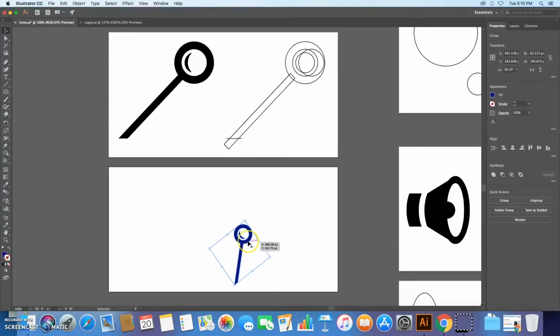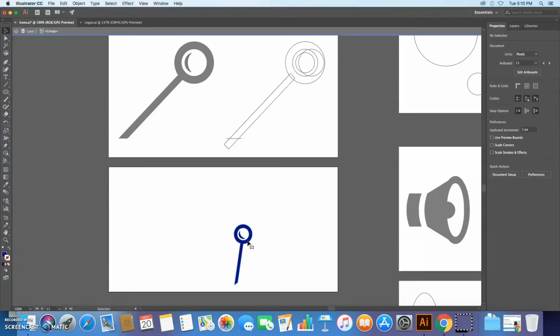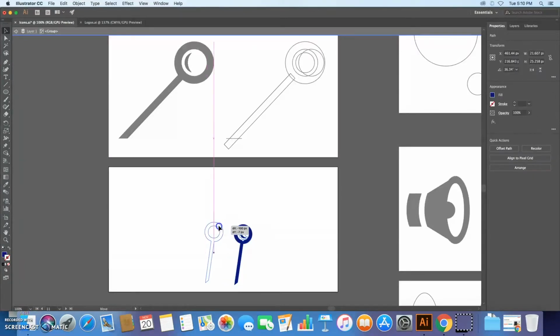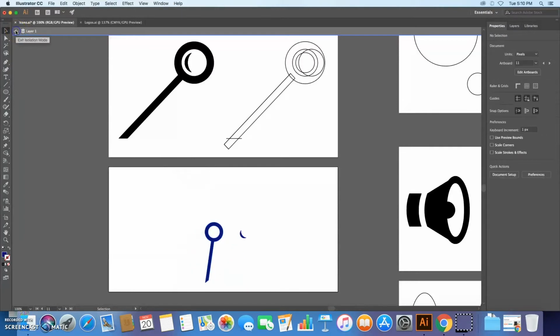And then if you double click on a group of objects, that brings you into what's called isolation mode. So you'll see this gray bar across the top of the screen, and every other object is kind of grayed out, so it's unavailable, because that means I'm focused in, I'm isolated on this group. And now when I'm isolated on this group, I can edit within the group. So if I move these objects separately, they move apart from one another. And then I just click this arrow to leave isolation mode.